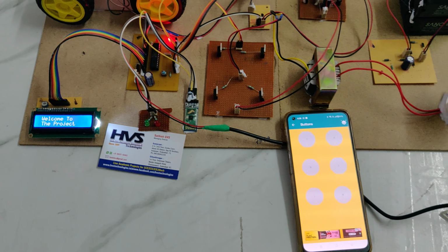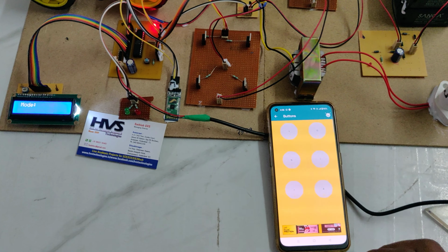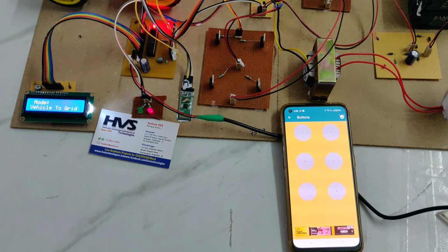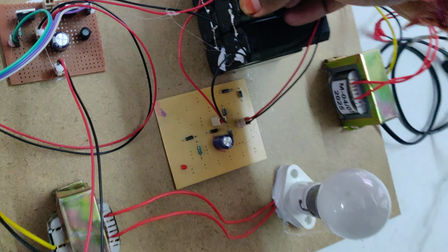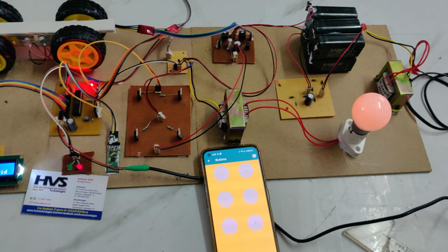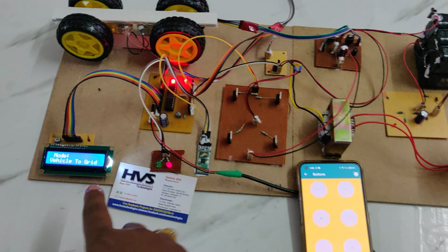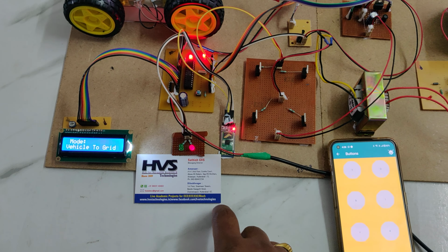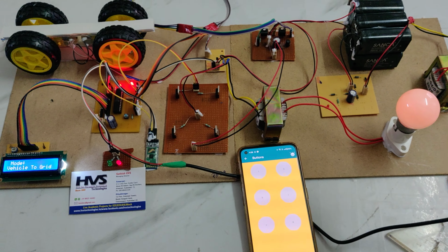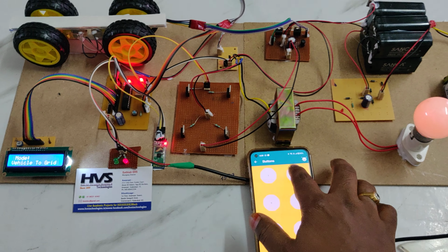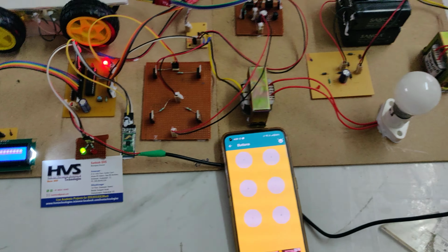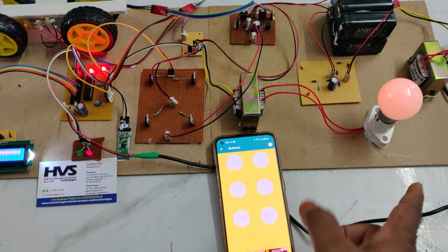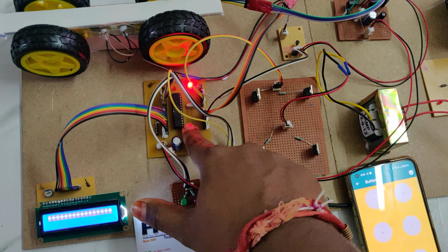While switching between DC to DC and DC to AC, meaning vehicle to grid and grid to vehicle, give at least a 2 to 3 second time gap. Now I am selecting vehicle to grid, as we have switched off the battery. Just switch on the battery. Now we are going to connect the vehicle section to the grid. Vehicle to grid is selected and the red LED is indicated. Now the vehicle is connected to the grid for DC to AC utilization directly. When I place 0, the vehicle is running and the green LED is indicated here. Again it was connected. If any disturbance occurs, you can just reset the system.